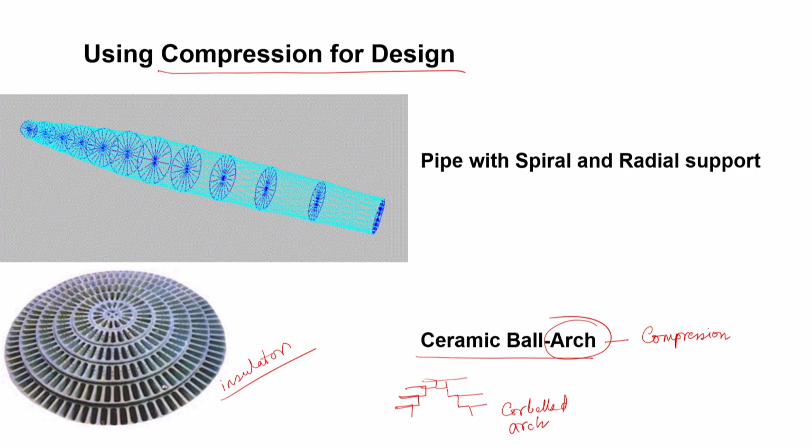So, starting from this corbelled arch, people started thinking: instead of expanding small by small, if I lay the bricks not horizontally but vertically, then you are going to get a complete arch system, with the stones or bricks arranged vertically with mortar. What is the advantage here?